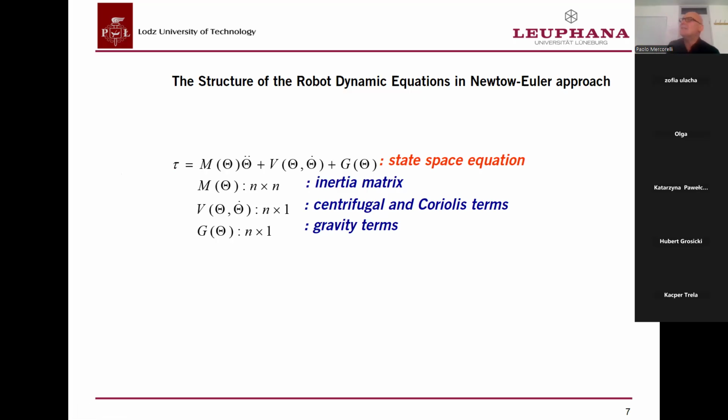In our easy example, we will see also the matrix too. But in any case, if the articulated system, the robot, is easy, sometimes we collapse it into scalars. But very interesting, this inertia matrix, this M, which characterizes the inertia of the system, is a function of theta.